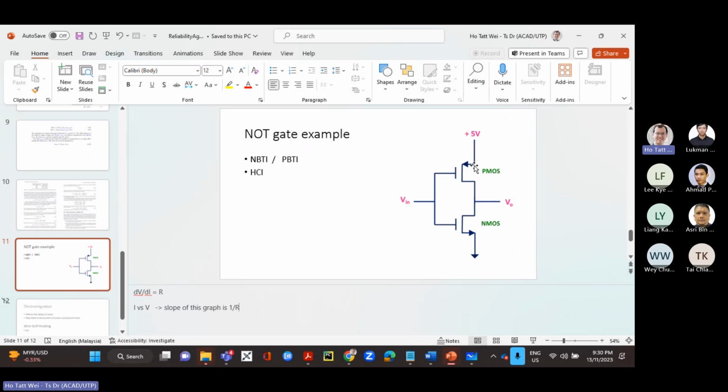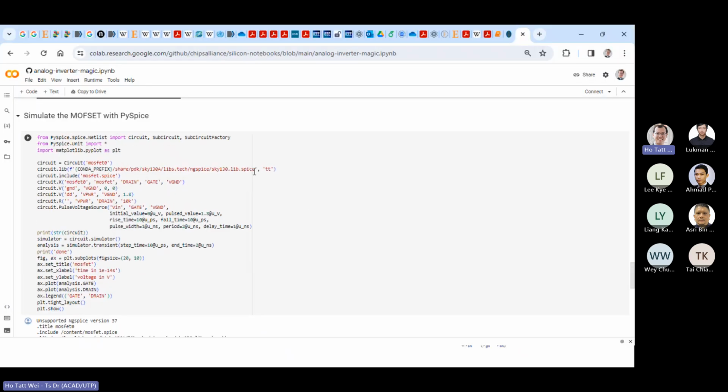And where we're going with this is because you understand that the delay model that we have is actually an RC time constant, right? The C is basically the load capacitance at the output. How you get the timing is you see what the effective R of the PMOS is, so you get the RC, or the effective R of the NMOS, you get the RC. So now you can see where I'm taking you with this simulation.